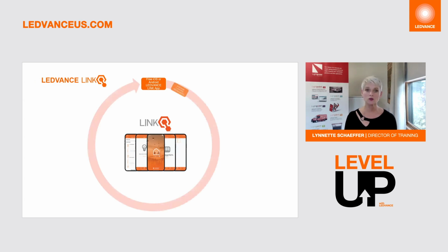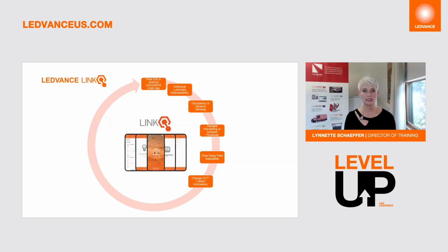So you get individual luminaire addressability. You also have the ability to set occupancy or vacancy sensing. You use the app to do that. Depending upon the sensor that you purchase, you either have daylight harvesting or ambient threshold. You can also set time delay. On some select luminaires, you can change the CCT. You can also select your high end and low end trim. You also have the ability to do zoning and grouping.